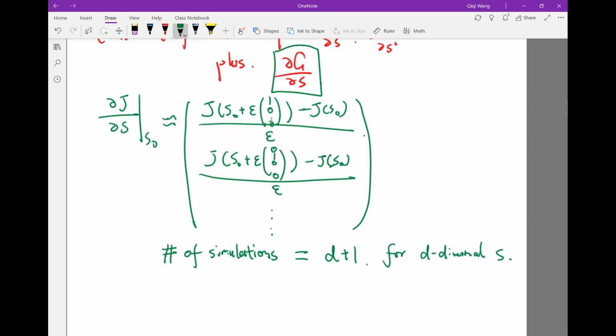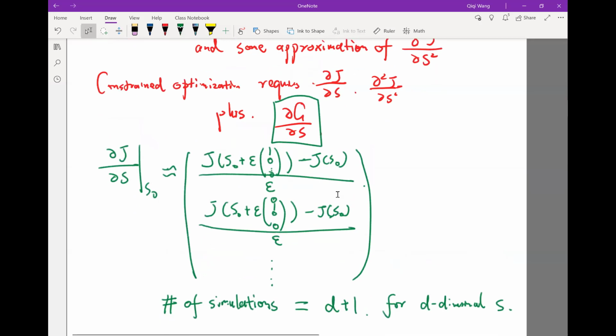If you're designing an airfoil, for example, you have 10 or 20 design variables. It's pretty common to use finite difference to compute such derivatives, not only for the objective function, but also for the constraints. It becomes more problematic once you start designing a three-dimensional surface, like an airplane wing. When you get to the regime of hundreds of design variables, the computation cost gets out of hand pretty easily.